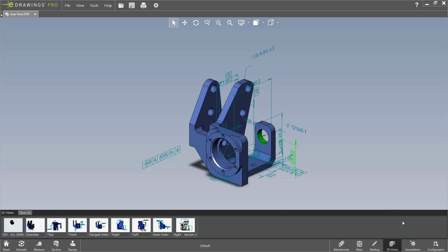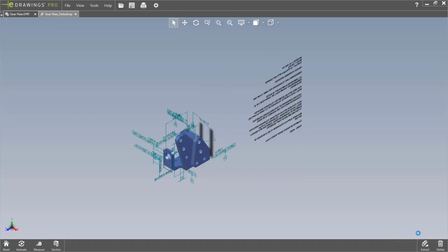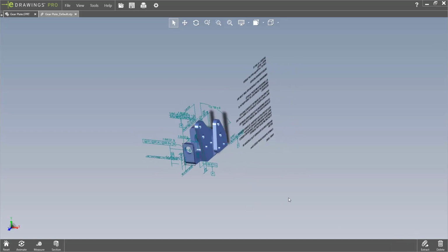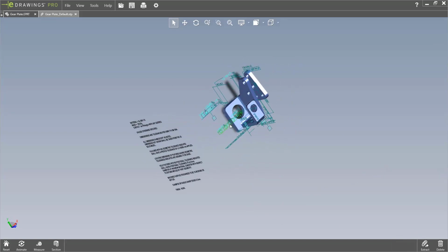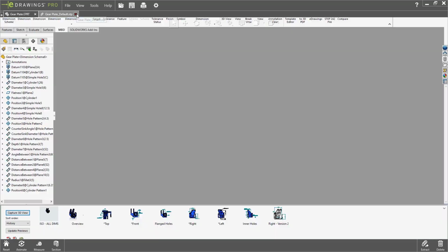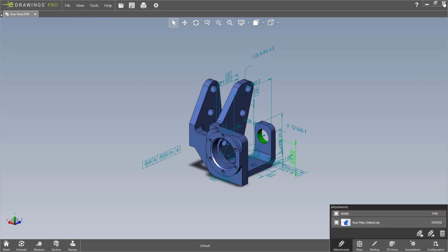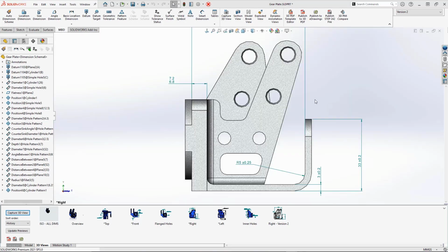When we exported this to eDrawings, we also included that STEP 242 attachment. Now we can either view or extract this attachment. The extracting will allow this to be a separate file that can be used for any type of machining. But if we just want to view it, we get a good idea of what exactly is included in this STEP 242 file. And we notice here that we get all the same 3D PMI plus the text from those notes. So again, attachments can absolutely be included inside of the model-based definition export.